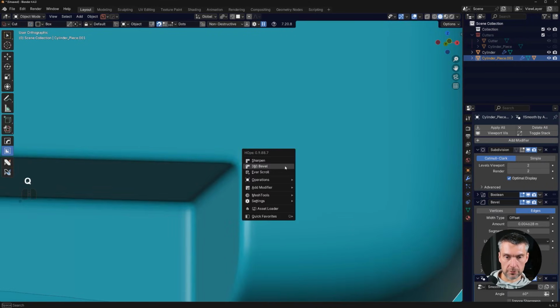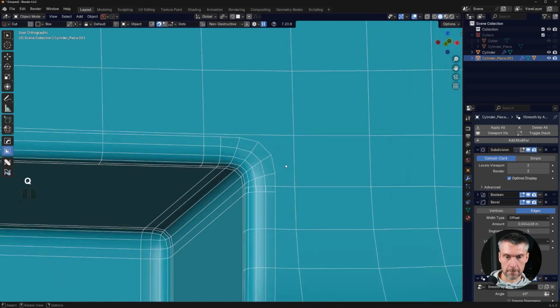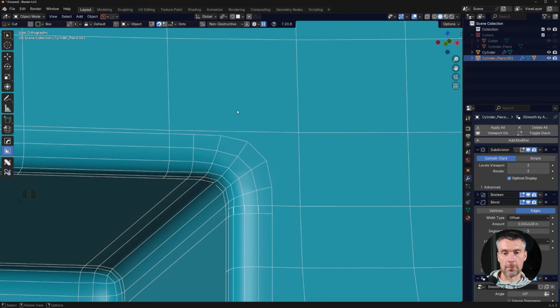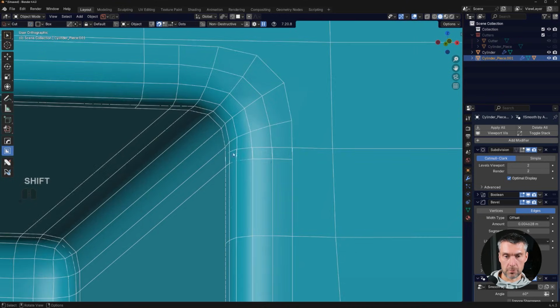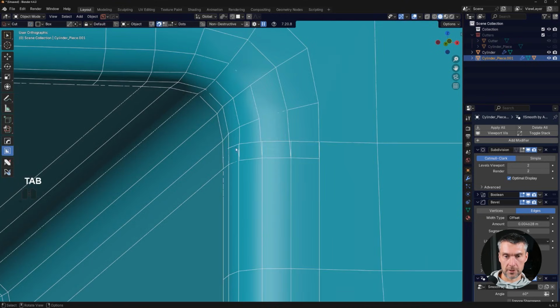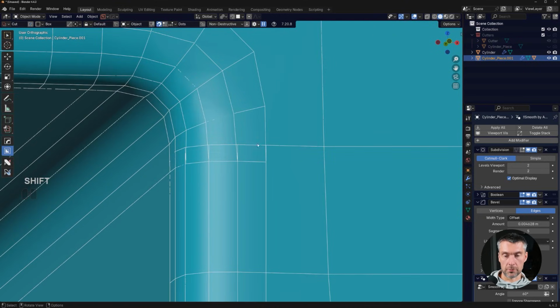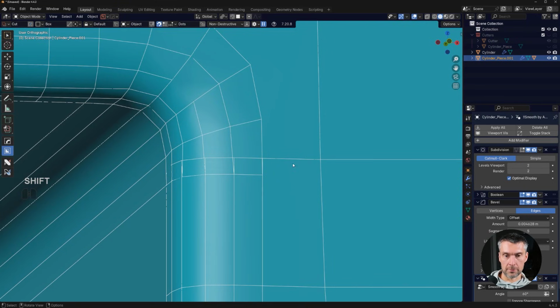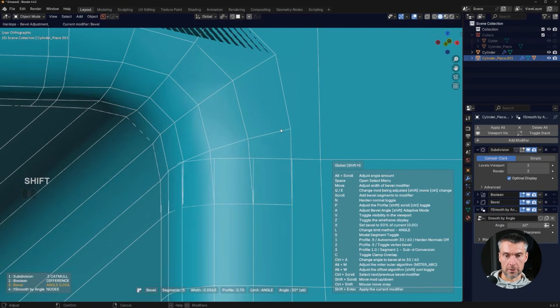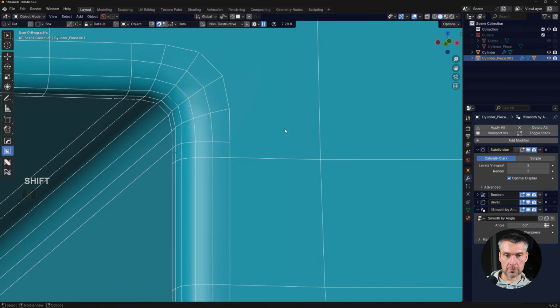If I go here to wireframe, right? You see this bevel. If you apply this, topology here is not connected to anything around it, right? So the reason, for example, why I got this shading problem here is because the edge created by the subdivision is going to overlap with the bevel. So if you wanted to make this go away, you need to make this bevel even smaller, okay? And I think maybe we don't need that many segments.